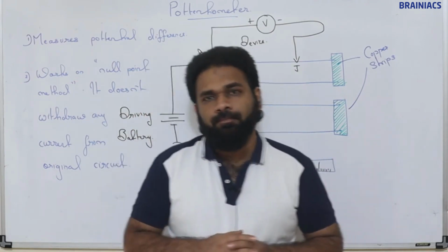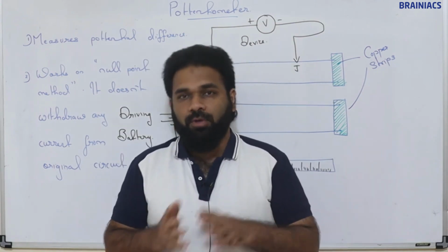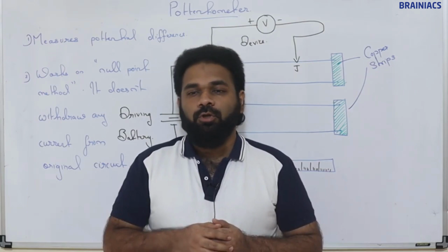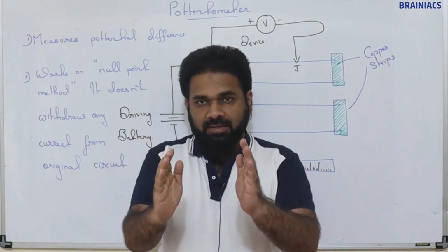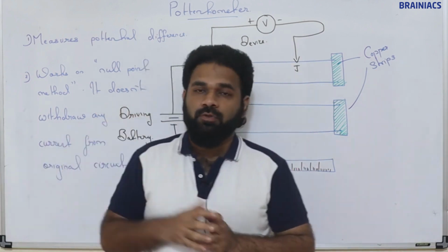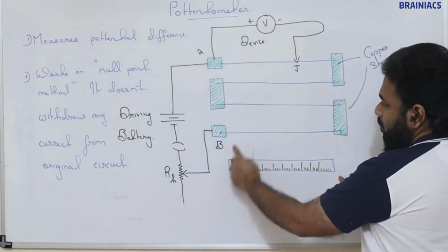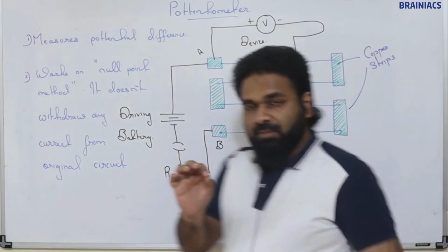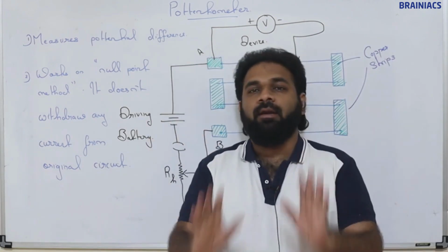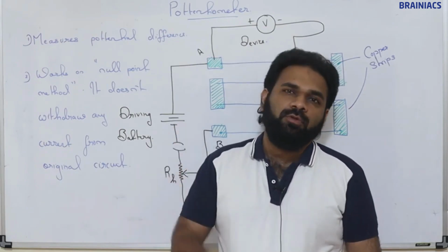But it is bulky. When we try to calculate the voltage or potential difference, we have some labor work here. With a voltmeter, we just connect it, look at the instrument, it shows the reading, and our duty is over. But here it is not so. You can see here, this is a scale. We will have to take some measurements and do some manual calculation, but the correct reading is guaranteed. But here we have some work. So it is not that easy to use a potentiometer.